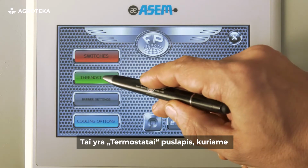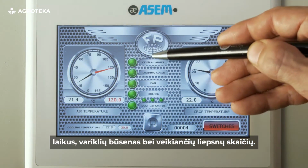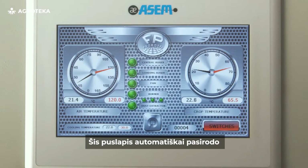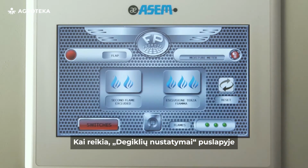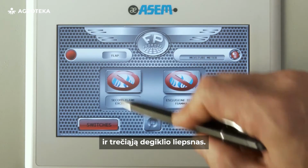This is the thermostats page, where you can constantly check the functioning of a dryer, the target and actual temperatures, timings, engine states, and the number of working flames. This page will appear automatically after several seconds as a screensaver. When needed, in the burner settings page, it will be possible to exclude the first and the second flames of the burner.